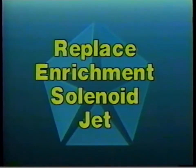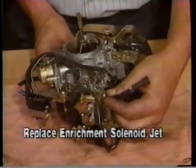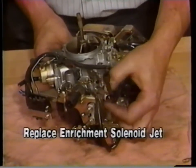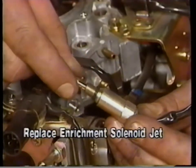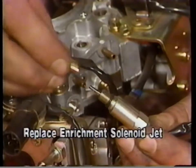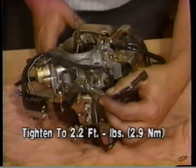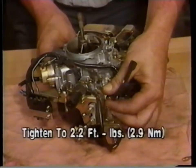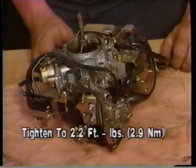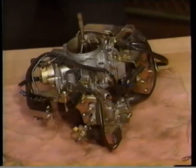The next part of this procedure involves replacement of the enrichment solenoid jet. To do this, locate the enrichment solenoid valve on the carburetor directly above the accelerator pump housing and remove the valve from the carburetor. Now replace the enrichment solenoid jet with a new jet from the emissions parts package. After replacing the jet, reinstall the enrichment solenoid valve and tighten it to 2.2 foot-pounds or 2.9 Newton meters. Again, do not over-tighten the valve since this will distort the valve and cause an over-rich condition.